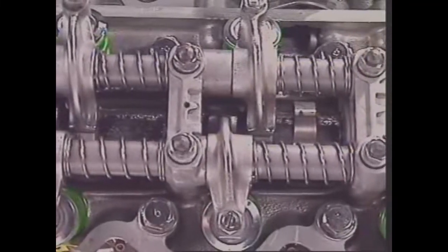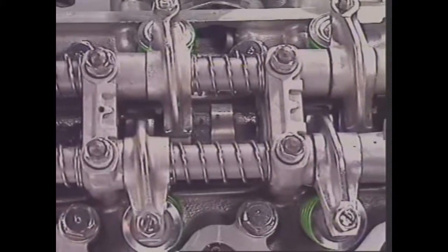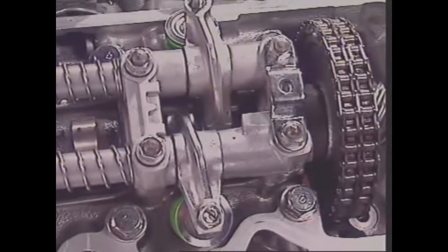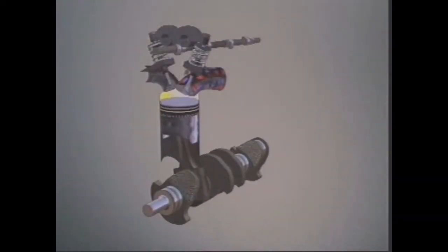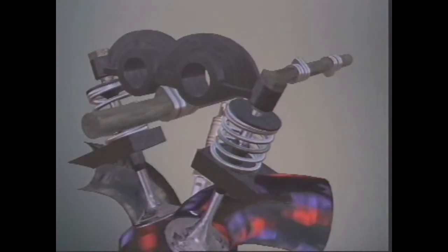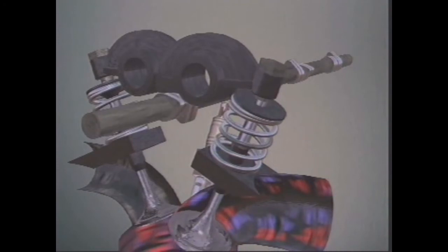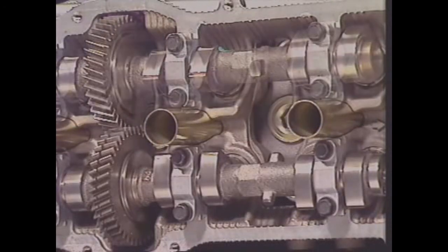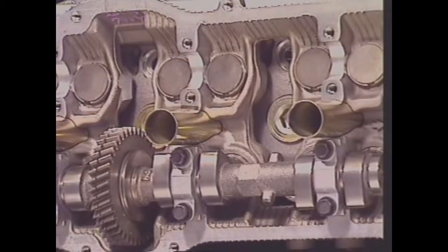The cams control the valve action, but what drives the cams? Cams are attached to a camshaft. In modern vehicles, it's usually mounted over the cylinder head and is called an overhead camshaft. Intake and exhaust lobes can be on the same shaft, or there can be a shaft each for intake and exhaust. Notice that in this design there's no need for rocker arms. It's a much simpler arrangement.